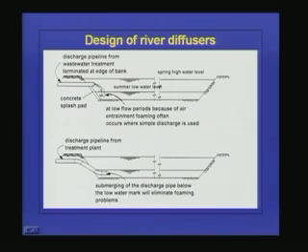This is the discharge pipeline from the wastewater treatment plant, and here we usually give a concrete splash pad to avoid erosion. At low flow periods, because of air entrainment, foaming often occurs where simple discharge is used. That is another drawback of this system, because in summer or at low water level the water is falling from such a height, and because of the turbulence and air entrainment, foaming can take place.